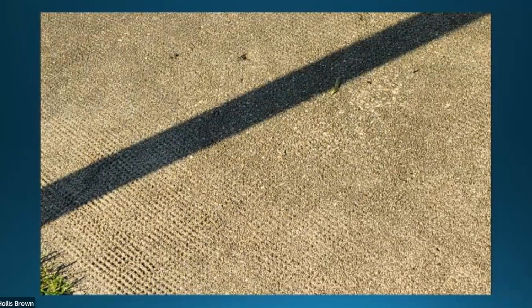It's burlap, right? It's not an anti-skid deal. When I was a kid, they were doing this all the time. Back in the day, in the 30s and 40s, concrete technology was really at an apex, and people were pretty detail oriented. So when they poured concrete, they would put burlap on it, and they would keep that concrete wet for a week. And that's how you get good, strong concrete.